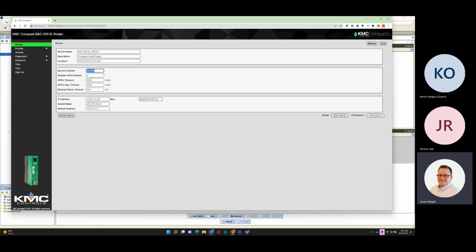Okay. So all these numbers that I've recorded and compiled, as you guys expand your building automation systems with all your other contractors you work with, there needs to be a time, and you should probably do it sooner than later, that you get a couple contractors together and you sit down and say, hey, when you guys lay out my BACnet networks, what numbers are you using? Are you going off the octets we give you? What are you basing that off of? Because at some point, these are going to overlap and you're going to be upset because it's going to be pulling data in from another school if it has the same instance ID.